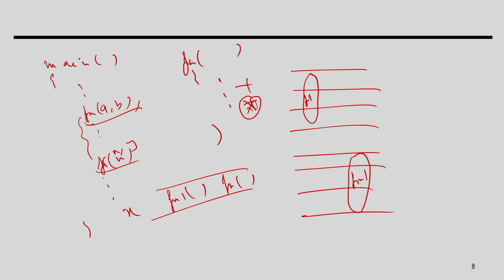Since they are scheduled in different time steps and their execution times are non-overlapping, it is just like a normal thing. The function might have a multiplication operation followed by an add operation. The multiplier takes 2 cycles and the adder takes 1 cycle. So, I can definitely have one copy of the module. If they are non-overlapping, the problem is easy.